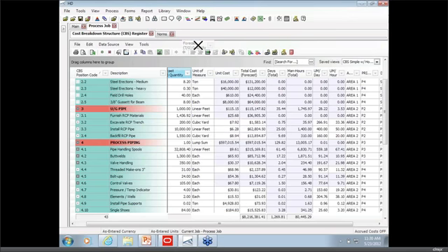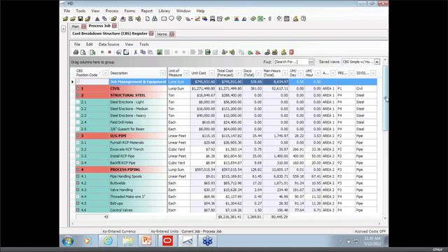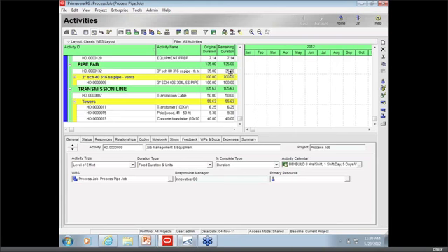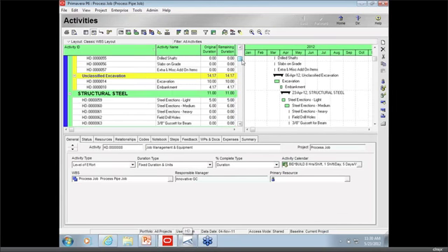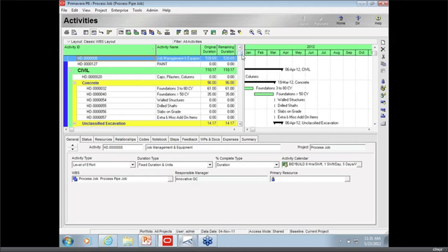Right? So each activity in my estimate is now assigned an area, a priority, and a division. What this allows me to do is rearrange my estimated items based on these tags in Primavera. These tags can be assigned to user-defined fields or activity codes if you have them pre-set up. So if I go into Primavera and scroll to the very top, I'm looking at almost the exact same structure that I have in hard dollar, that cost breakdown. And what I want to do is rearrange it based on my area, my division, and my priority.